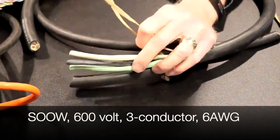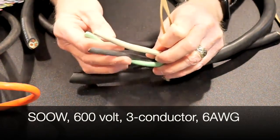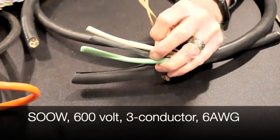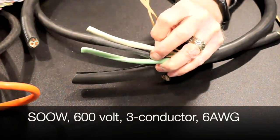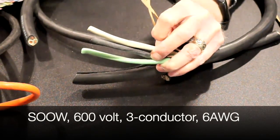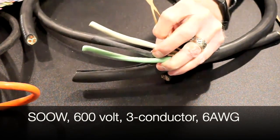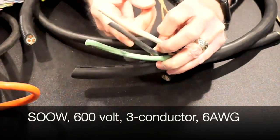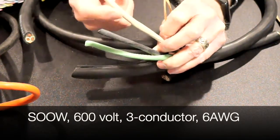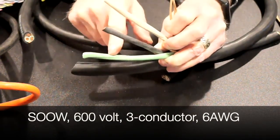So 3 conductor cord, you have to be careful now when you specify this cord. We're not talking about just the current carrying conductors. We're talking about the total number of conductors in the cord. Now this is 6 AWG, so we might see it abbreviated 6/3C, something like that. 6 AWG, 3 conductor. So there are 3 conductors. We have our ungrounded conductor with the black insulation. We have the white insulation on this conductor, and then we have the green for the equipment grounding conductor.